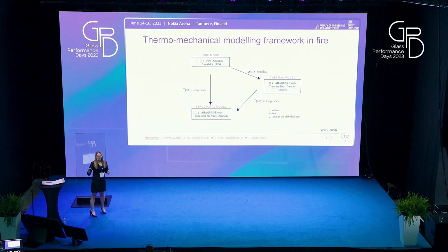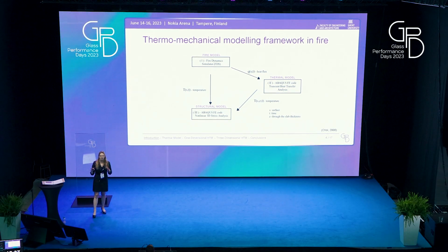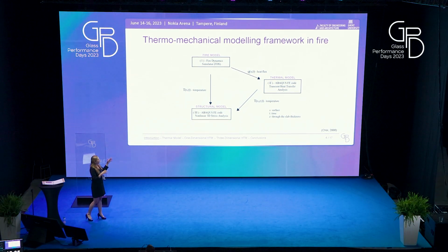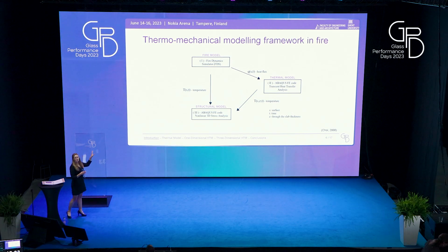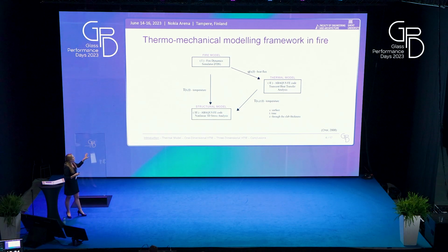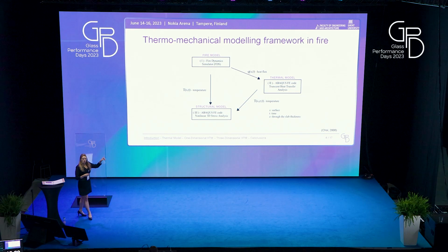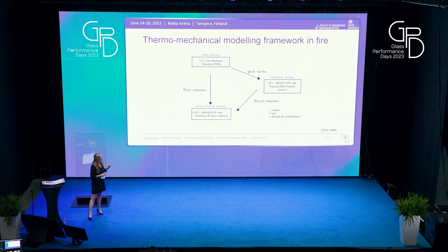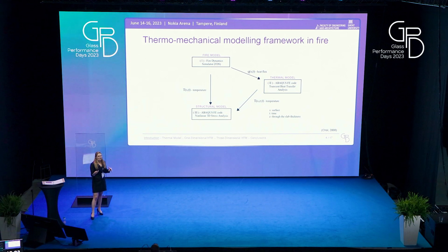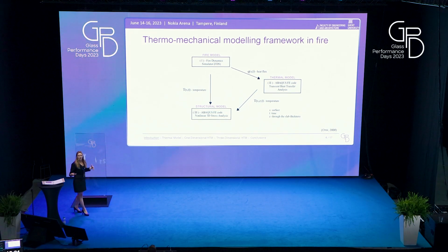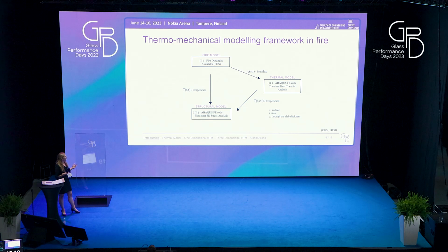So when we talk about modeling structural elements in fire, you have a general framework that always comes into play. So you have a combination of 3 different models. You have a fire model, a thermal model, and a structural model. So you start with a fire model. From the fire model, you get the heat fluxes from the fire, and you get the temperatures of the fire.